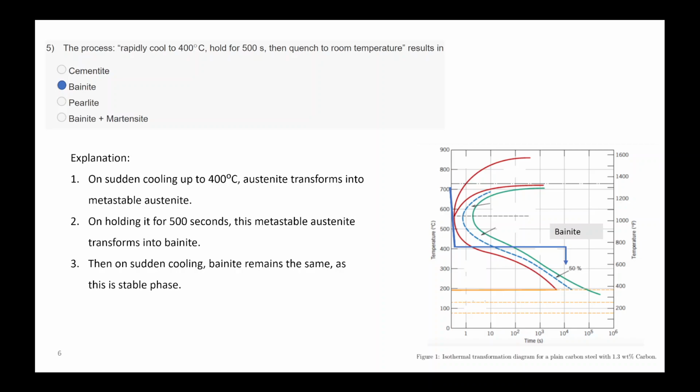In case of fracture mechanics, you are considering that certain defects are already existing. When you are talking about the engineering stress strain curve, then you are assuming that your material is defect free. Then you get a particular tensile strength, and you assume that only up to that particular tensile strength or fracture strength will your material fail.